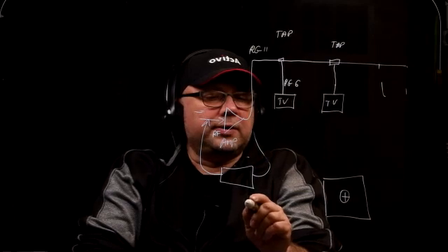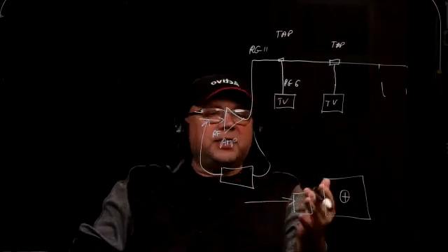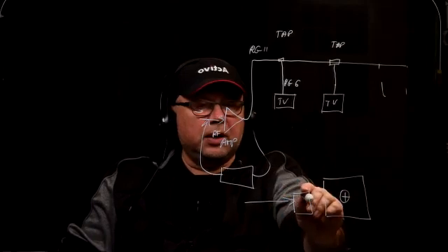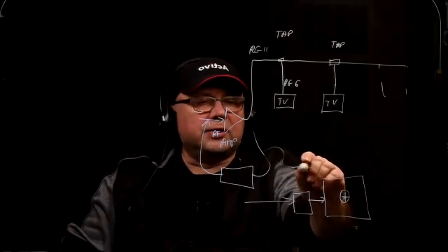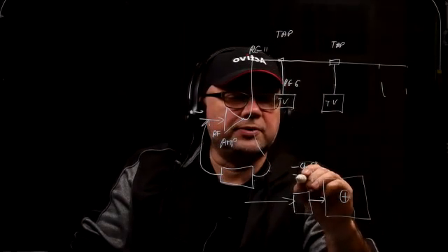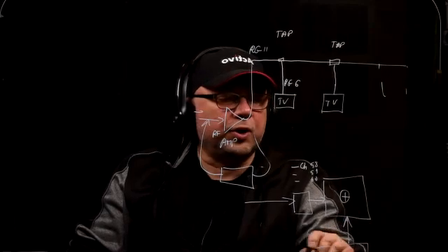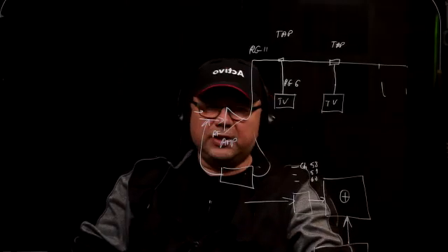And you get the signal from the city going through a filter where you filter out, let's say, channels 56, 57, and 58. So those channels are going to be eliminated from the whole cable TV coming from here, and it's going to go into here, minus, let's say, channels 58, 59, and 60. Okay, minus. So those channels are not going to exist there. And over here, you're going to inject your little broadcasting studio for your high school that is going to broadcast on channels 58, 59, and 60.